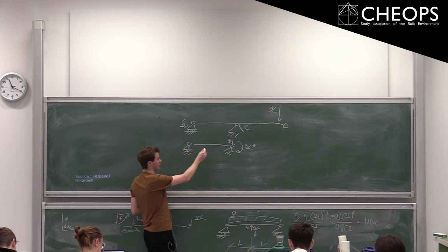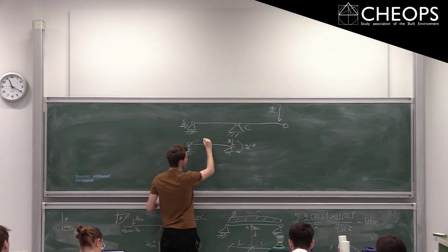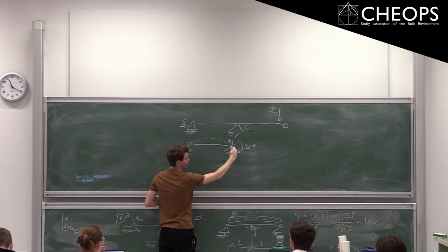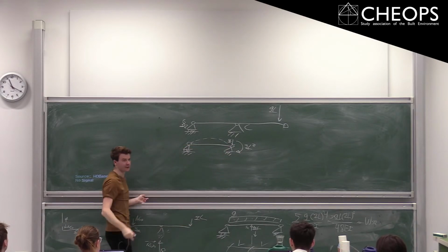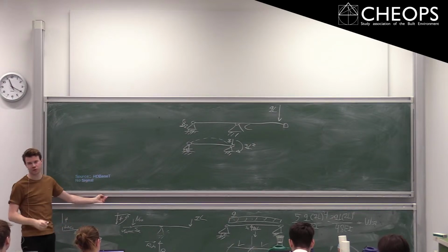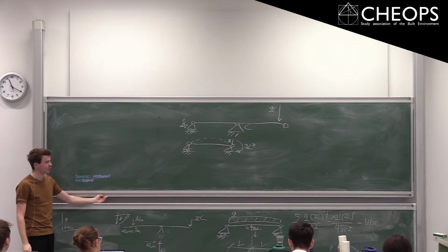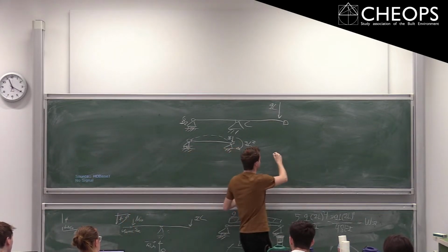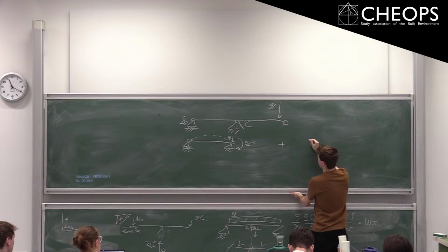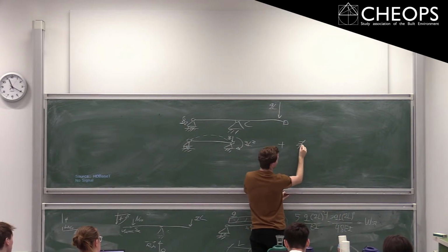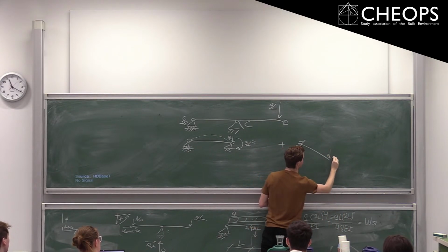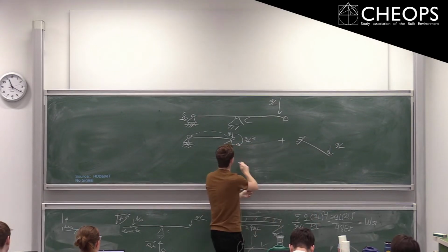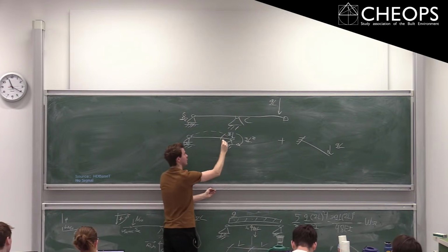If you look at this carefully, you know that because of the bending moment moving upwards, this part will become under an angle. And that's actually, of that first multiple response exercise, going to be that inclined beam effect, right? Because the second step we will do in a second. Over here you get basically like this, very, very exaggerated. And this angle is the one we need to calculate. That's this one.